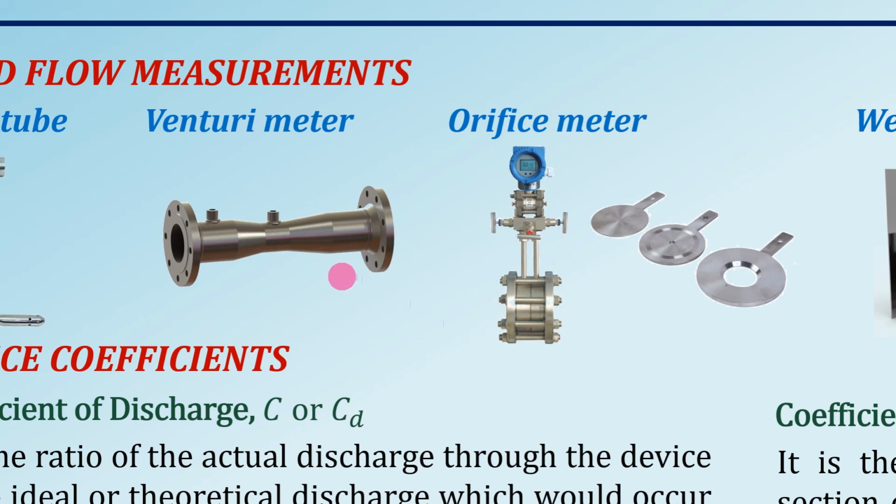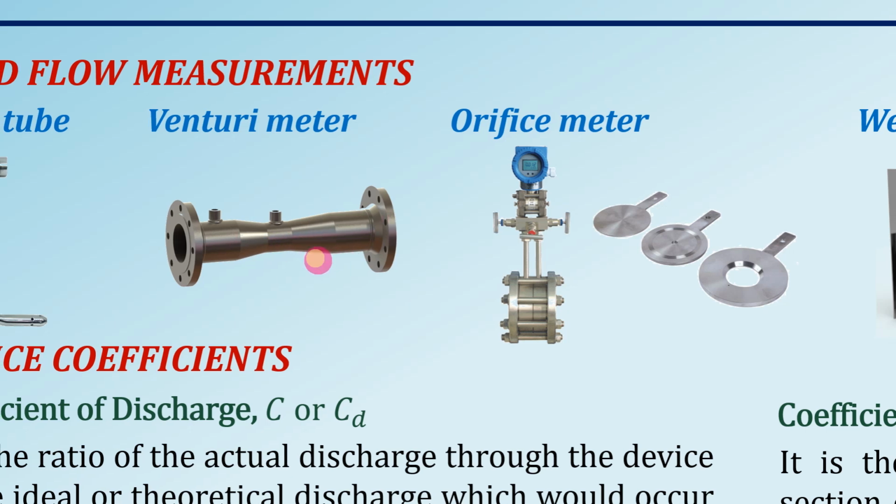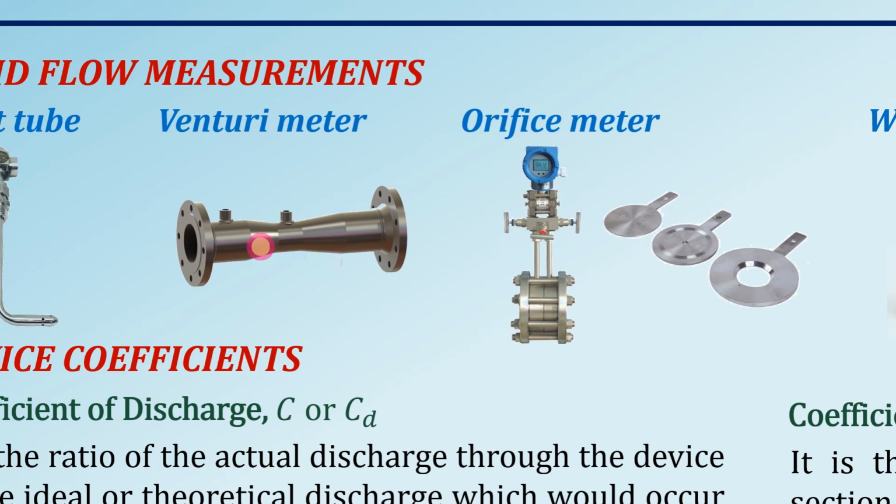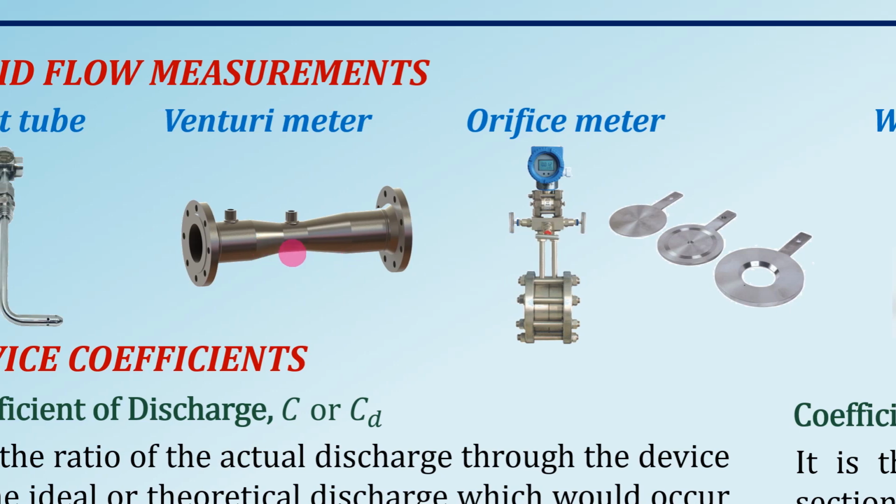So, ang venturimeter natin, ina-attach sa isang pipeline, then we have a converging and diverging na section wherein from a larger na cross-section, lumiliit tayo, no? Lumiliit yung cross-section. Then, after lumiit, no, we have the throat. After nyan lumiit, babalik tayo sa dati niyang cross-section. Bakit ba natin pinapaliit yung cross-section? Para magkaroon tayo ng changes in velocity and the pressure. So, yung relationship ni velocity and pressure, yung ginagamit natin to calculate the Q using Bernoulli's energy equation.